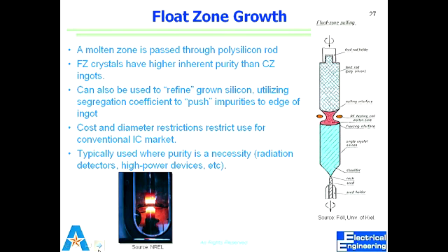Once we start moving, the float zone is simply a zone where we have molten the silicon. Once we move it to the top, the lower part follows the orientation of the seed. Right? So what results is crystalline silicon.